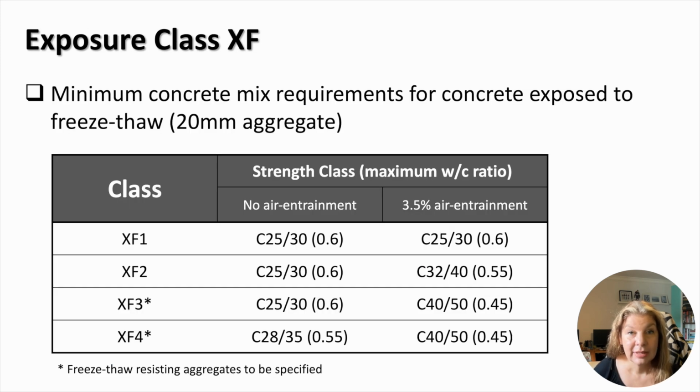One of the environmental conditions relevant for concrete is XF, that considers risk of freeze-thaw attack. In this table, strength class of concrete are defined for several severities of this type of exposure, depending on whether air entrainment admixtures are used. Since porosity is an important factor that limits the effect of freeze-thaw on concrete, the water-cement ratio is kept high in the case where no air entrainment agents are added.